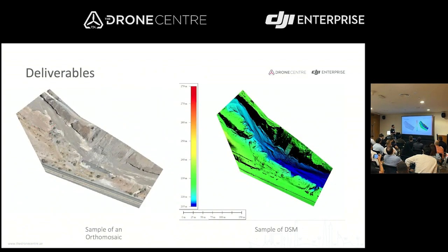We can see here the ortho map, ortho mosaic, with less than 3 centimeter GSD. We can determine everything, even the rocks, because for this project, you remember last year there were heavy rains in Fujairah, so many rocks fell down and covered the pipeline. When you zoom in, you can recognize all the rocks on the pipeline, the trees, everything, because this is good resolution.